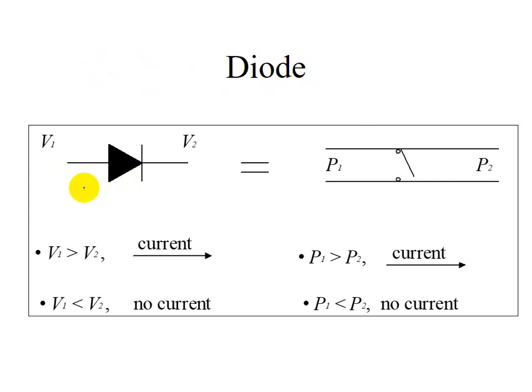A diode allows the electrical current to go through in only one direction when the voltage is forward biased. It will not allow current to go through if the applied potential is reverse biased. When you have bias for the P and N, with the P side connected to the positive and the N side connected to the negative polarity, this is so-called forward bias.